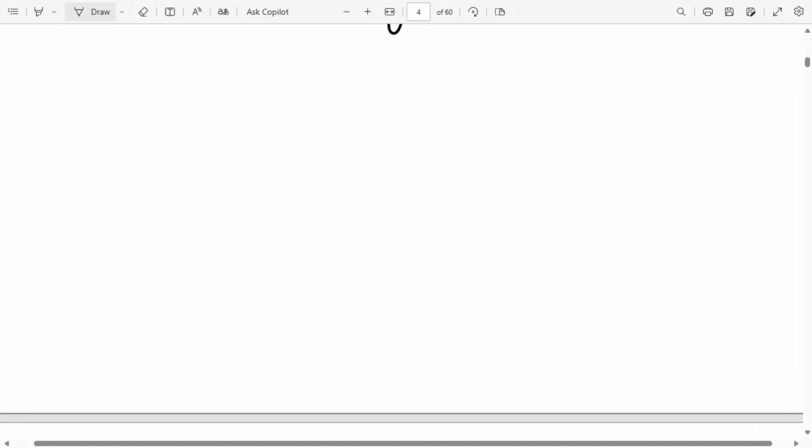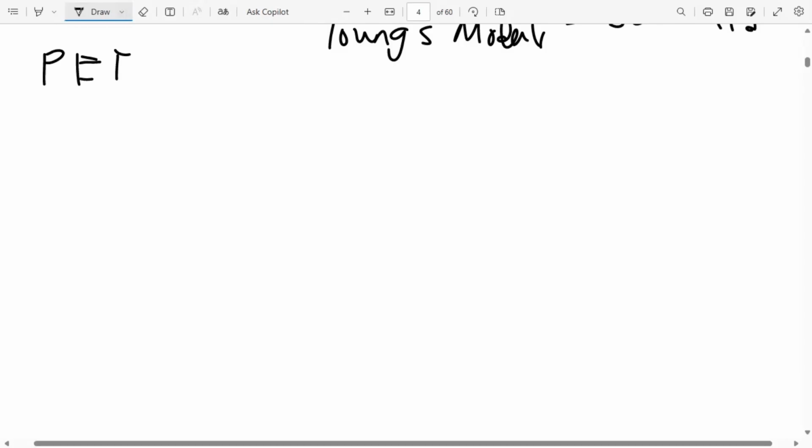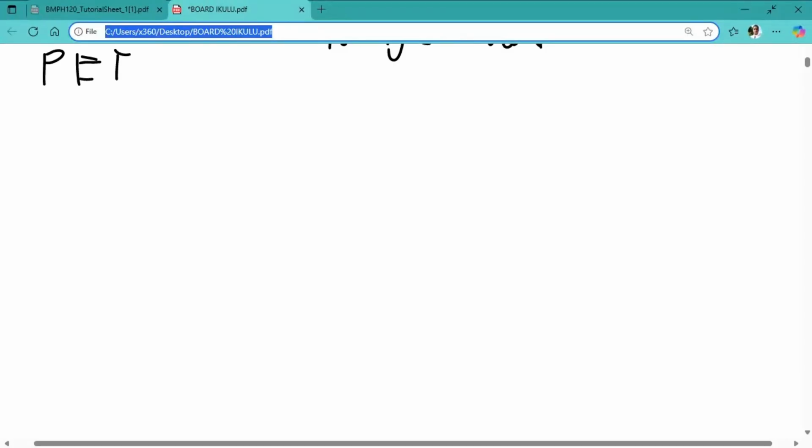If we also look at the synthetic graft materials, an example is polyethylene terephthalate, or mostly called PET. Its Young's modulus is 1000 to 1200 megapascals, and these are much stiffer. Sorry, these are synthetic ligaments. It's stiffer than the natural ligaments, since the one we've calculated is 529.